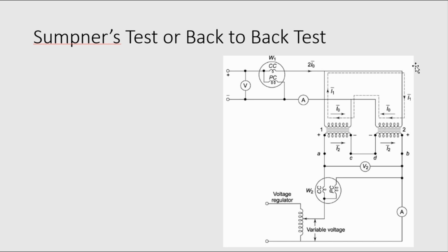Okay, so this is the basic idea of using open circuit, short circuit and Sumpner tests instead of doing it in actual full load condition, that is to save energy. Okay, so I think we have concluded the basic fast revision of the transformer. So we'll try to create more videos about other machines also at a later time.